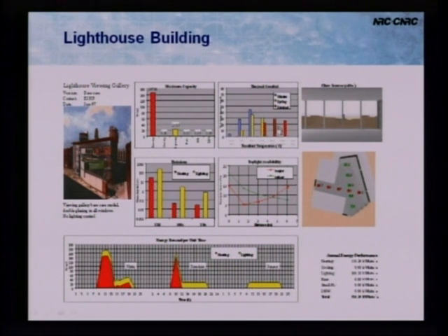We can see what our thermal comfort is. It's not so good in winter. It's getting pretty warm in there in summer. Glare sources, looking out these floor to ceiling windows, there's no glare sources because it's so well lit that there's not a contrast issue. Looking at daylight factors, there's 2 images here. So the red curve relates to the red dots across this floor plan of this area here. Very well daylit, so there's not a problem with the amount of daylight that's coming in there.